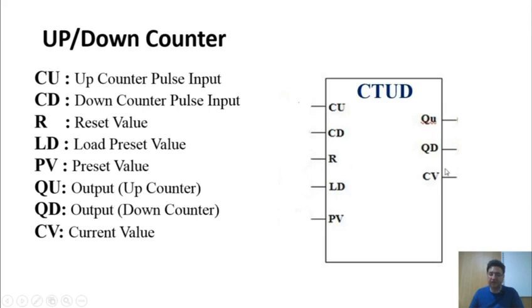For our counter to work in decrement mode, it is essential that before the counter is activated, we preset it at least once using this LD terminal. This presetting operation is directly related to the proper functioning of the down counter mode, which is also known as the decrement mode. If we want to operate in decrement mode, we must perform a preset here at least once. Here is also the PV value, meaning the counting value that the counter can perform is entered here.